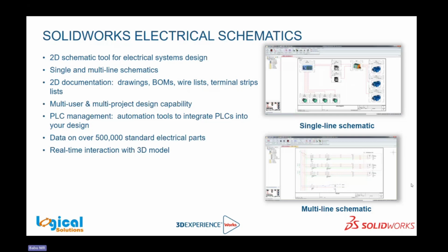Okay, when it comes to SolidWorks Electrical schematics benefits, it's a 2D schematic tool for our electrical system design, where we can create our single line diagram, which is the image you can see. The SLD shows how the components connect between each other with a representation of a single line. And we can generate multi-line schematics also, which is the detailed circuit diagram of the complete system, showing from which terminal to which terminal the wire is connected. It could be power line schematics or control line schematics. Everything you can generate here.